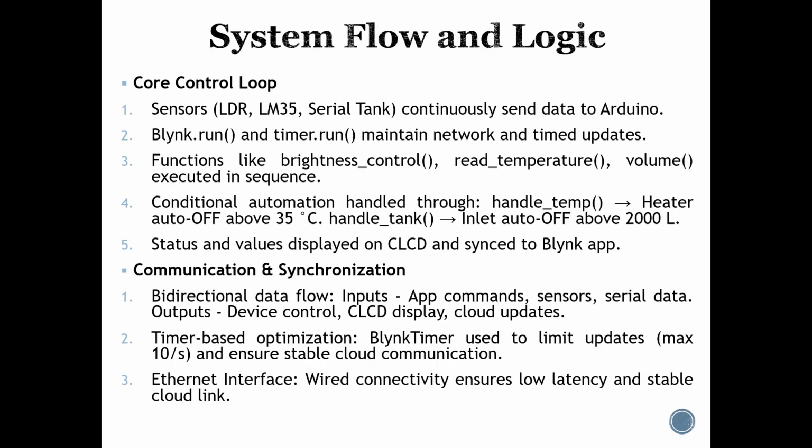Here is how the logic works. Sensor readings from the LDR, LM35, and the tank are continuously taken. Based on threshold conditions, control actions are triggered automatically. Data is updated to Blynk Cloud using virtual pins. Inputs from the Blynk app are read and executed by Arduino in real time. This combination of local automation and cloud connectivity represents a true